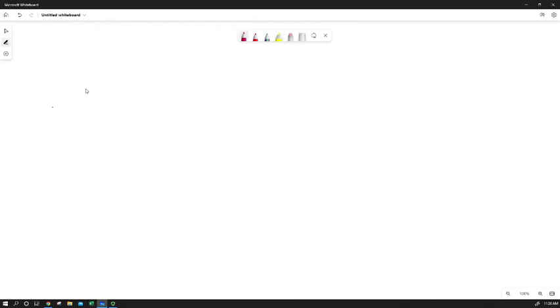You could derive this with any configuration of circuits, provided that you know what the charge on the capacitor is at a given starting time, and you know the resistor and the capacitor, so that you know the time constant. This is called the universal time constant expression for an RC circuit.